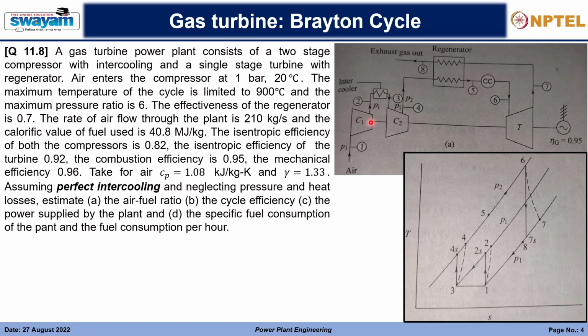Between each compressor, the temperature of the outlet of the compressor is cooled down, and this is a lower temperature, as you can see. Although the pressure is rising at the compressor, with pressure the temperature is also rising, right? So the temperature is then cooled down at the same pressure. Again, the compressor raises the pressure from a lower temperature to that particular temperature. You can see from this T-S graph, it will be better here.